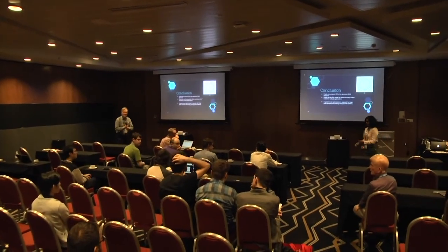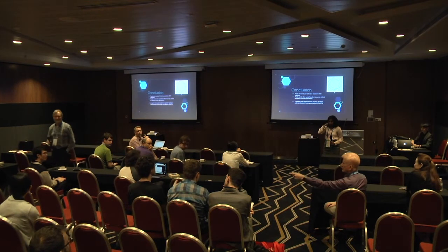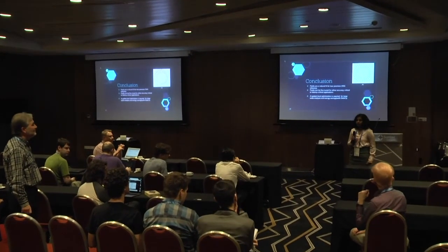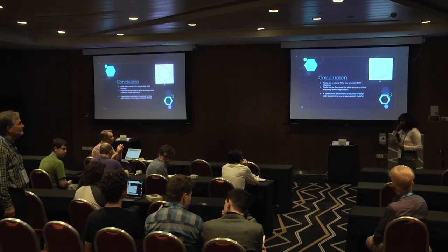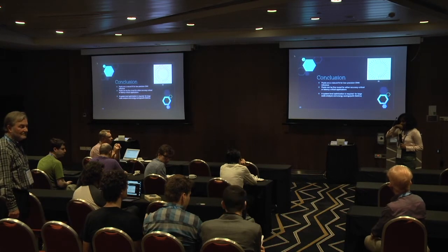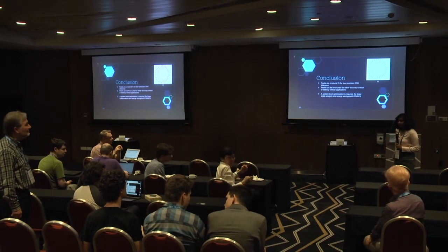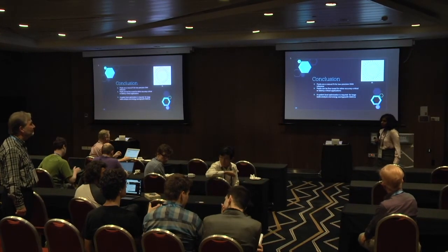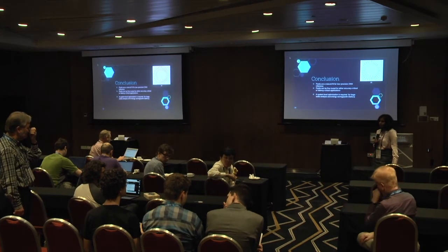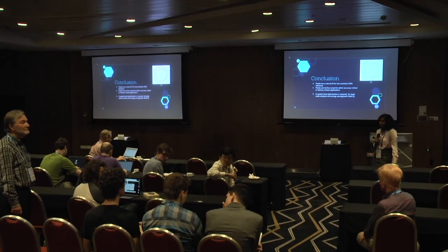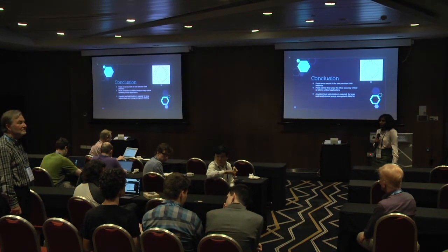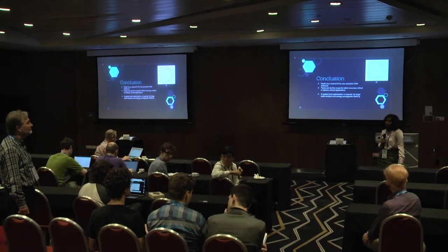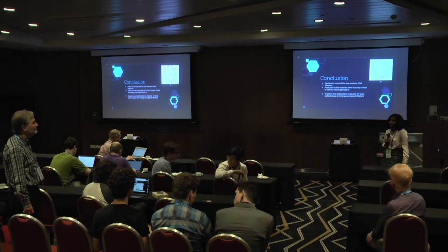Just to make sure, you never have an overflow in your EMAC in these applications? Yeah, we are clipping. But you never have such a large sum that you would risk overflow? You're clipping at the ReLU, I'm not sure I understand. The answer is probably that yes, there's no overflow because the wide accumulator is wide, but just to make sure, because for small precisions, I'm not sure. The accumulator remains quite small. The wide accumulator that we used is 32-bit. So you never accumulate that many values. Yeah, okay.